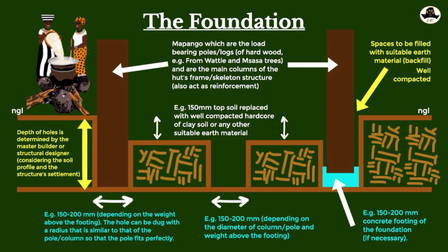Some people use used oil from mechanical appliances, but that oil prevents water from the underground from seeping through the wooden poles, because they come from trees. I would encourage hardwood or indigenous trees, especially in Africa, because they have better properties in terms of durability.